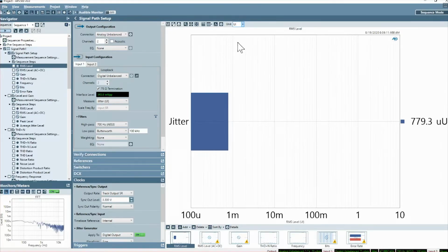We're measuring the digital interface itself, and now we're looking at the amplitude of the jitter that's coming in from this device. And this is where I was referring to an entire UI being quite a bit of jitter. The residual jitter of this analog to digital converter is less than 1 micro UI or unit interval, which is a sample rate independent view of jitter.